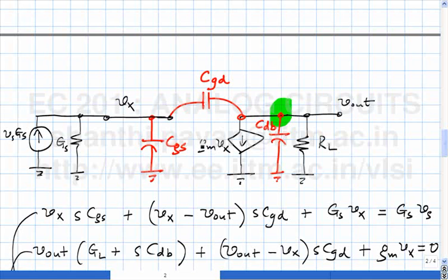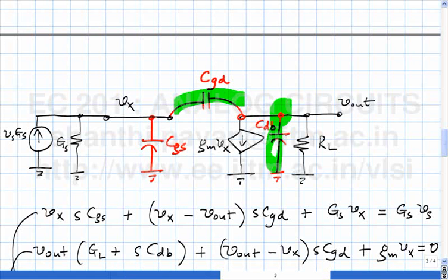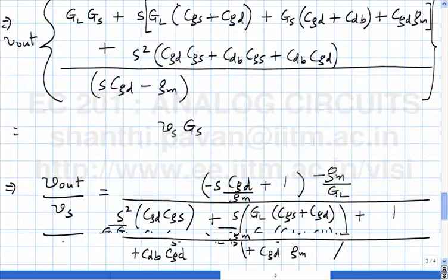So in other words, the order of the network is the number of capacitors minus the number of capacitor loops. When there is a capacitor loop, all the capacitors in the loop will not be independent. One case in point is here where it is sufficient to just specify the voltage across this capacitor or this capacitor, and this capacitor to figure out the voltage across CGS. That's why the order is 3 capacitors minus 1, which is for the capacitor loop. So this is a second order system. So that also makes sense.